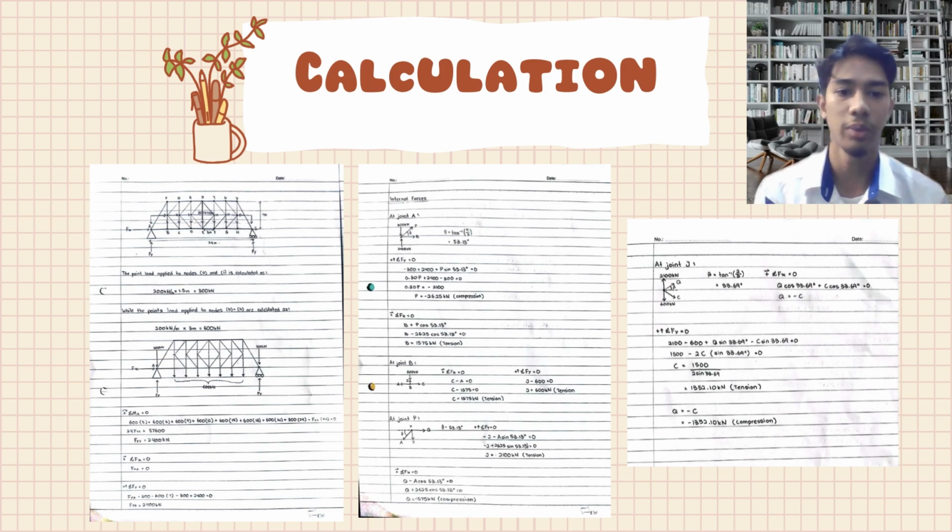We're moving to joint B. Using the sum of Fx equal to 0 and the sum of Fy equal to 0, we determine that the force in C is 1575 kilonewton, which is under tension, and the vertical force at J is 600 kilonewton, also under tension.